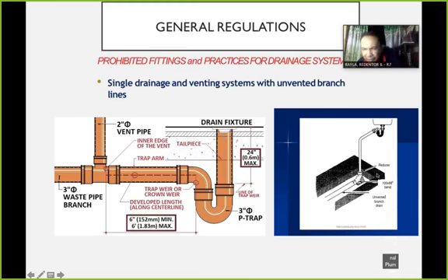No? We have our bend and unvented branch drain. No? So this is prohibited without any ventilation. So you will be asked in this drawing, what is the problem with this drawing? Okay, that is prohibition. Prohibited because there is no ventilation. Unlike this one, there is ventilation.